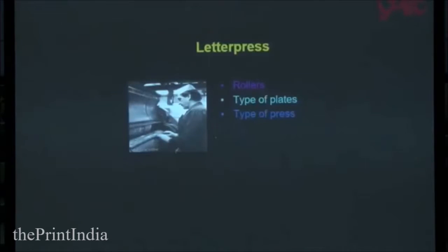Letterpress, again we have, don't think letterpress is obsolete process. Letterpress exists in its modern form today very widely. SL Propack, they print most of their tubes by letterpress printing. It's a photopolymer letterpress plates, okay? So most of the people, when they talk about letterpress, they think it's obsolete, it's old type and so on. You have to look at the modern letterpress process.